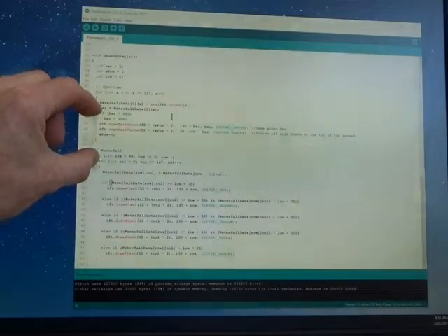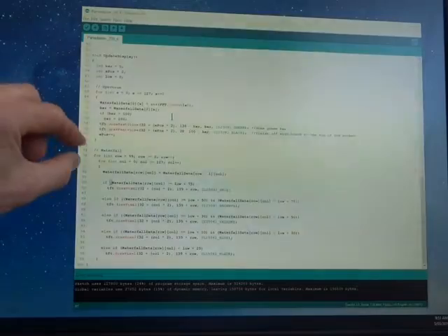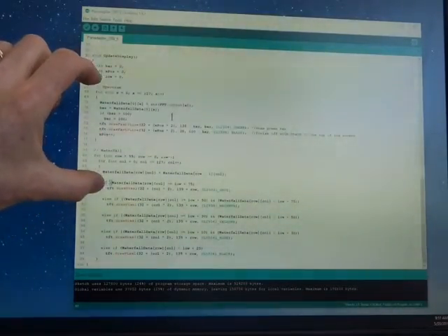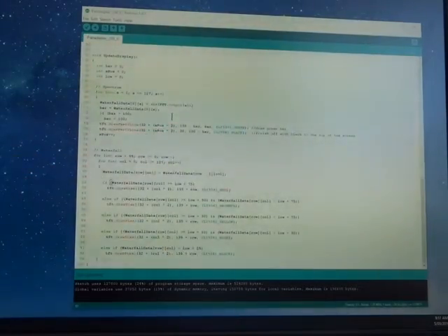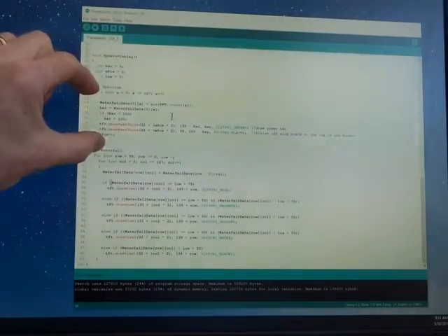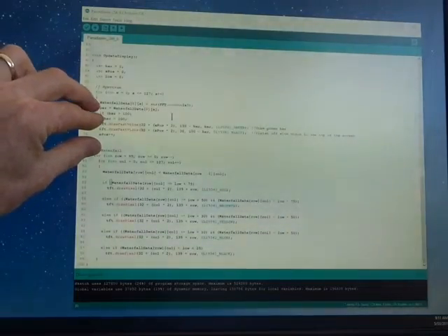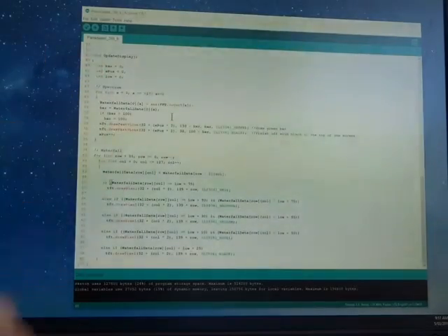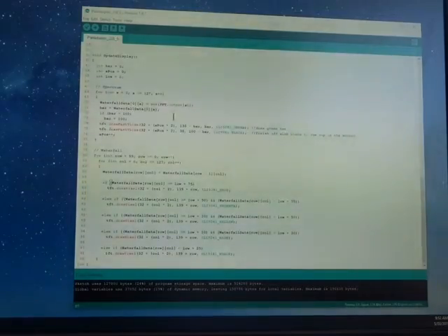The bar itself is drawn in green, and then the remaining portion for the height of that box that I've assigned for that spectrum is then drawn black. The reason why I've done the second half black is that the next time it goes through this, if that green bar has reduced, there's still a residual portion from the time before. So if I now overwrite that in black, we get a nice smooth display, and it always looks like a clean bar being drawn each time.